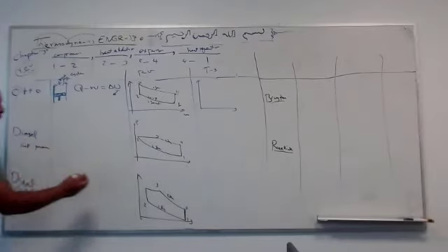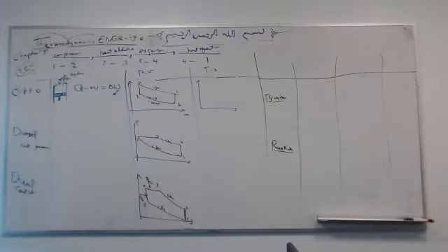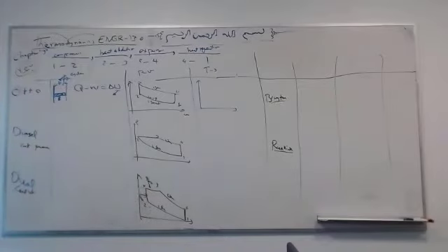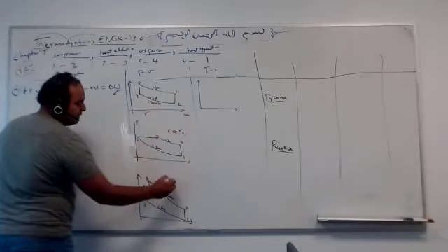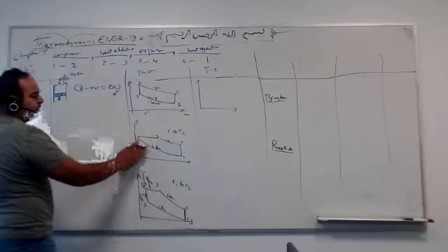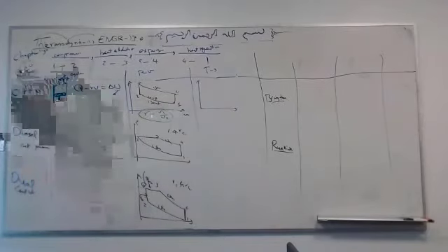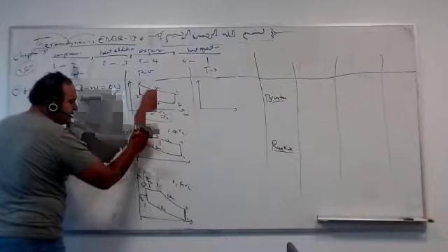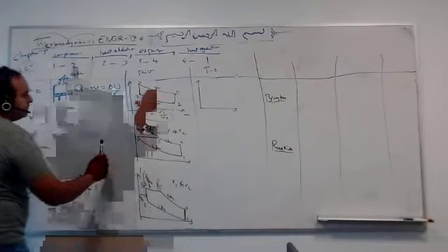So here in the table we have two heat additions, QH1 and QH2. The net heat is the addition of those two. So part of the heat is added at constant volume and part of the heat is added at constant pressure. I think it may be the dual cycle, I don't remember. Here we have R and RC. R is the compression ratio, V1 over V2, the biggest volume over the minimum volume. Actually, V1 equals V4 and V2 equals V3. RC is the cutoff ratio, V3 over V2. It's still greater than 1, but much lower than R. Here, V3 over V2 is 1, but here it is not.